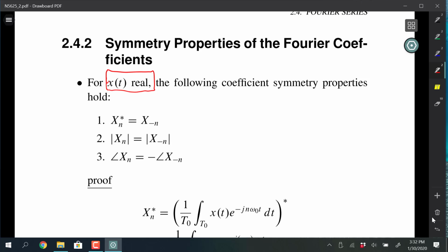The signal that you would be exposed to is an analog signal, and it would always be a real signal. But nowadays that we do software-defined radio, we get signals that are complex because of the way we process them in the receiver. So these 3 points aren't always valid here because sometimes we have complex signals, but still, as a good starting point, this is a good way to go.